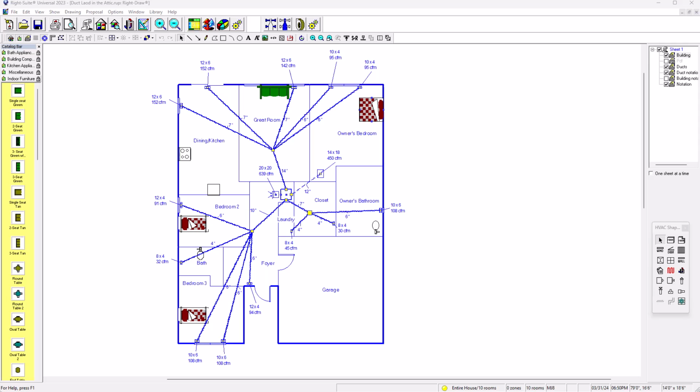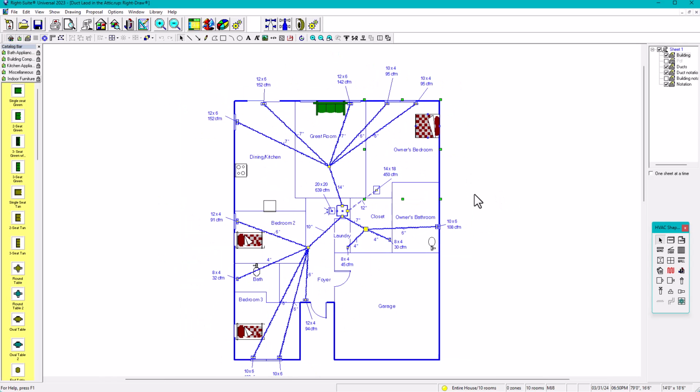So in here what we need to focus on, number one, is where the ducts are running. For example, this is one of the examples from a video I made before. This is a one-story house, a single home. And as you can see, this is my system and all the ducts are running in the attic. We have to be careful with that, because anytime you run your ducts in the attic, you have to have proper insulation, you have to seal your ducts very well, and you have to make sure they're installed properly.